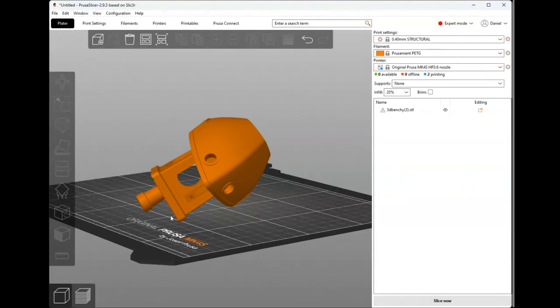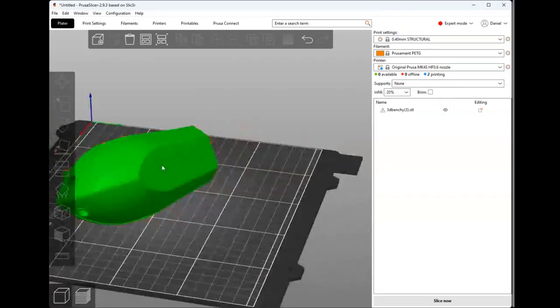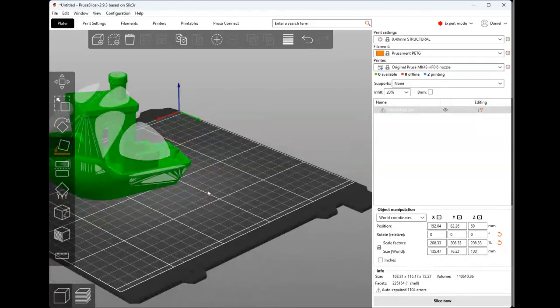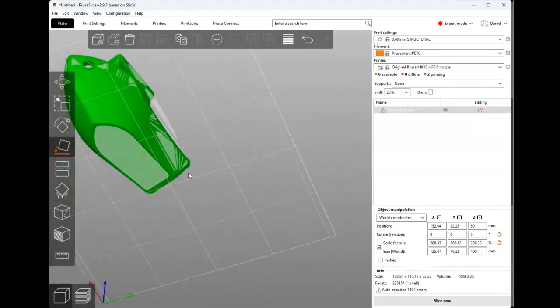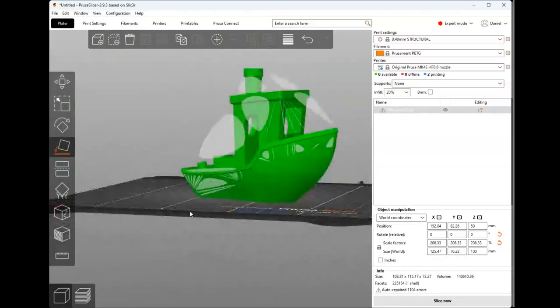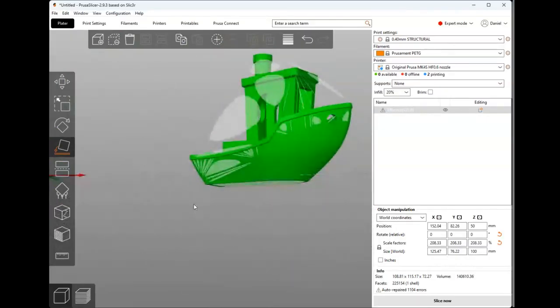So it'll be a lot of force on very little surface area, and this will probably break off and fail. We want to look for a nice flat surface that will support the model completely. And so that's why you have this. Most 3D prints have the bottom chopped completely flat.